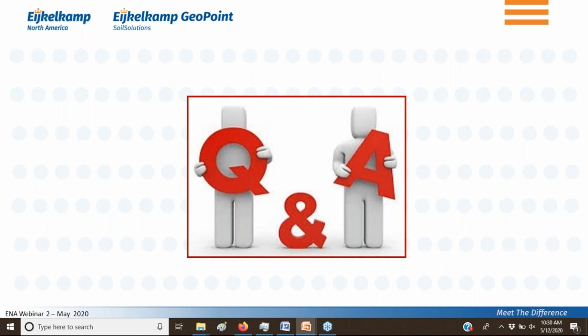Okay, I did want to point out too that some of the other webinars that will be given, one of those is going to be on the Sonic CPT cone, which is a cone that is unique that we came out with. A lot of times when you are pushing your cone and you hit a hard layer and you've hit resistance, we now have developed a cone that you can put sonic vibration on to get through that harder layer to continue your push.